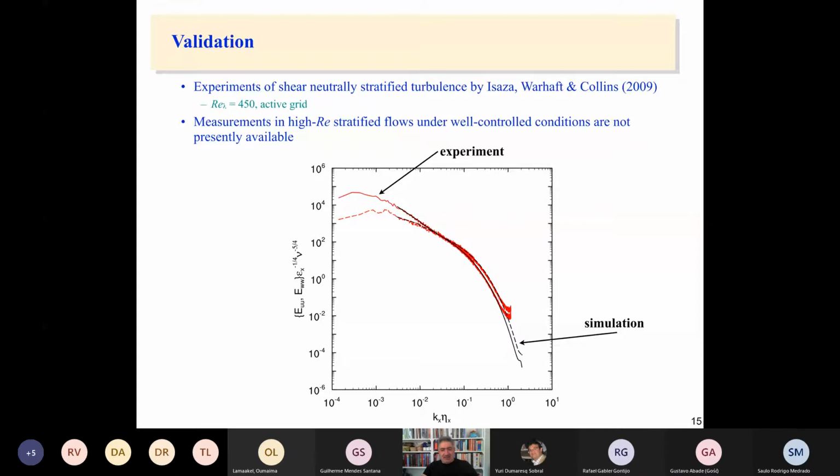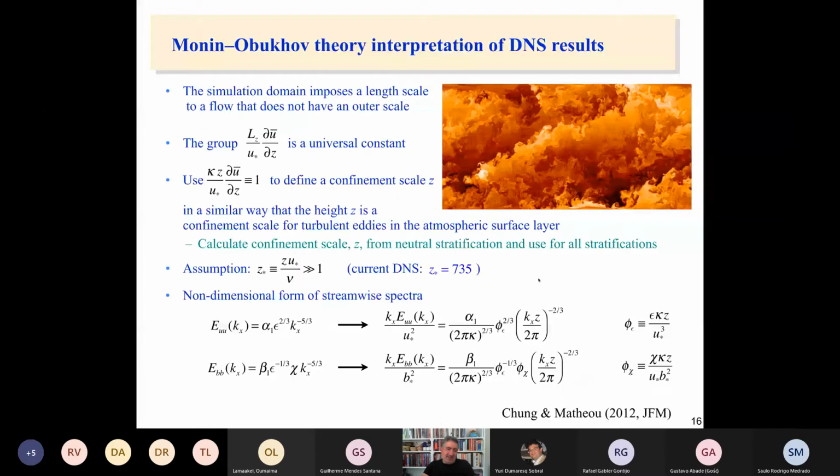So this is a nice thing, and this is what we are looking for when we are studying turbulence. We're looking for essentially these relationships where we have data, in this case the red is an experiment and the black lines are a simulation, but if you scale everything with the right parameters, then the data collapse onto each other. So we're going to take this scaling now to the next level. We're going to understand how our DNS works not in terms of this scaling, but in terms of TKE, dissipation and the length scales.